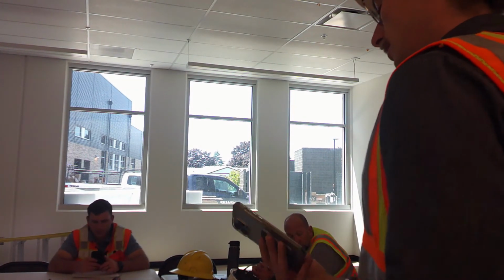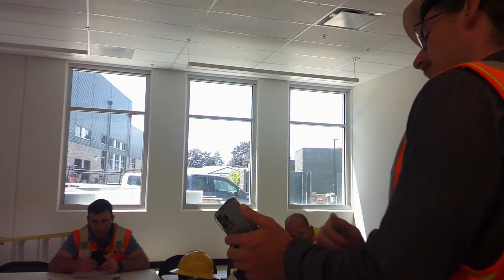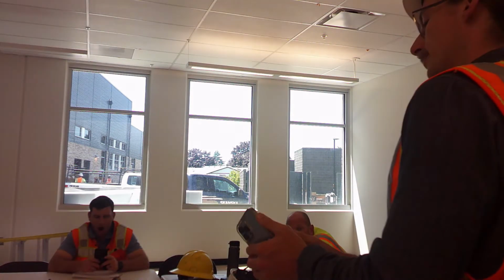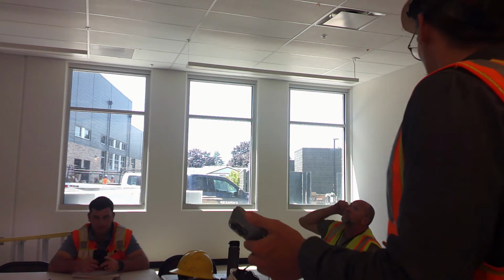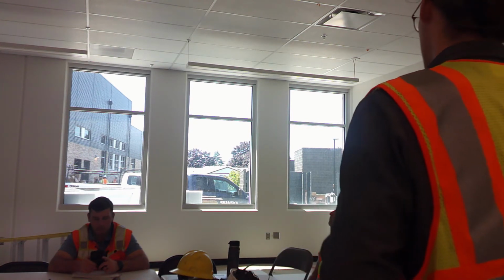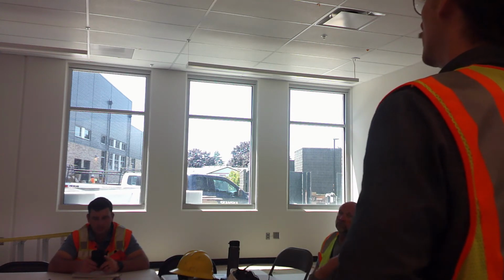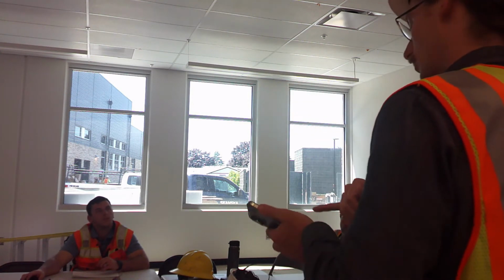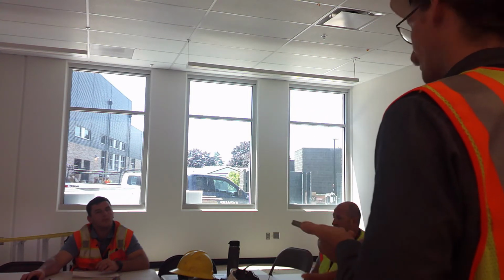Another useful thing in here on the app in the bottom right, or bottom left, we've got the override, where you can determine what groups the override is affecting, turn the entire room on and off, dim it up and down. Does that override the light sensor? I didn't notice. So actually, that's what I was going to say next. That photocell, whatever the level the photocell sets, you cannot put the dimmer above that. Even through the override, through the switches, through the area controller, no matter what you do, it's not going to go above that.